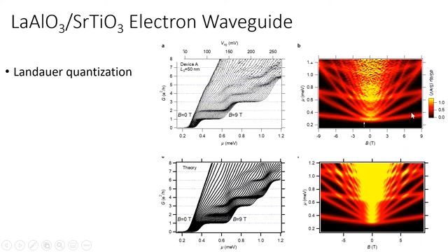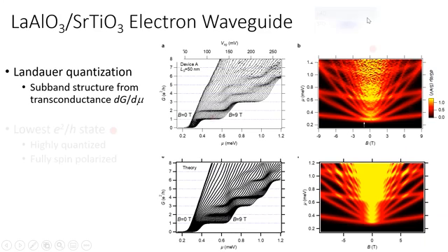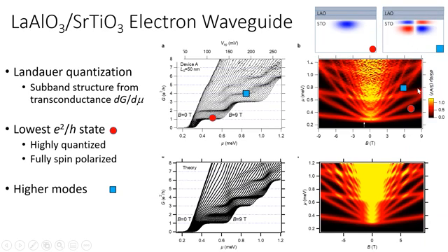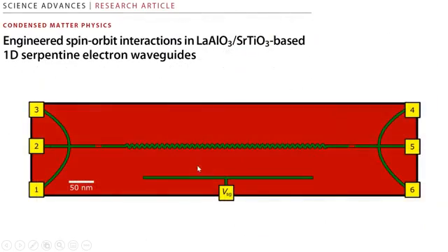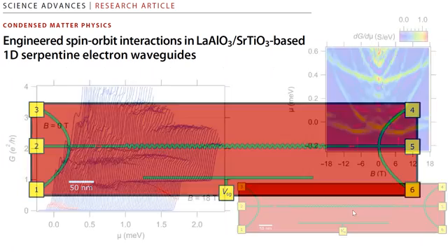So the idea is that we can essentially identify every one of these subbands with this model, but there are important deviations. But the point is that this is a highly ballistic channel that we're beginning with. We're working with a channel that is a straight electron waveguide. And so now what we're doing is we are modifying the waveguide and making it move side to side, and we want to ask what happens as a result of this change, this perturbation of the straight electron waveguide.